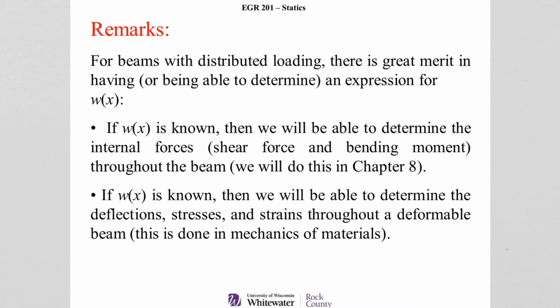So just a few quick comments about our distributed loads. If we have beams with a distributed loading, it's really important, if we can, to find an expression of this distributed loading in terms of x. There are some values of doing that. And one of them is if we know that in terms of x, we can then determine our internal forces in terms of x for our shear force and our bending moment throughout the whole length of the beam. And that's what we'll be covering in the very next chapter. So this method that we're going through right now is very important to know for Chapter 8.